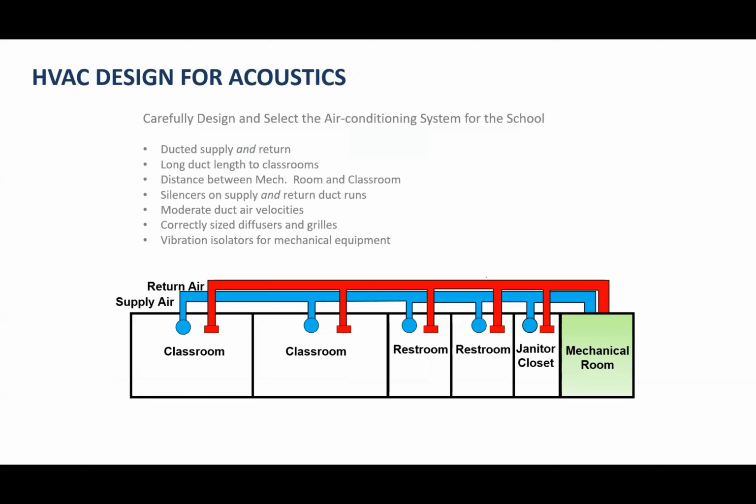Yeah. So as we were saying before, the background sound level can play a key role in the students understanding what's actually being presented. So HVAC systems can be very critical in helping maintain that signal to noise ratio that we were talking about earlier, where you want it to be at least 15 dB or higher. And again, with those younger students, you need even more, closer to 20 decibels above the noise is what you'd be looking for.